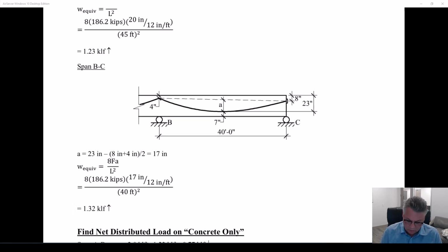And one thing to notice here is that as the spans get shorter, you will be balancing more load. These are also called balance loads, but this number is squared. So as that's getting smaller, this number is going to go up, even if the drape isn't a full drape. When I showed you that PowerPoint presentation and that concrete was exploding up, that was what was happening there. This span had become very short, and this drape, I believe they were draping as much as they could. That's what exploded that concrete up in the air.